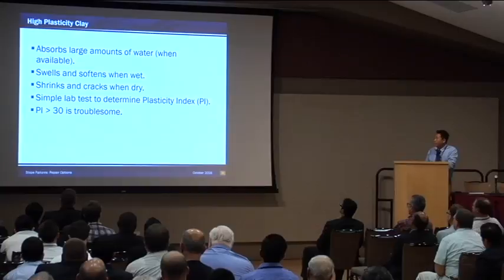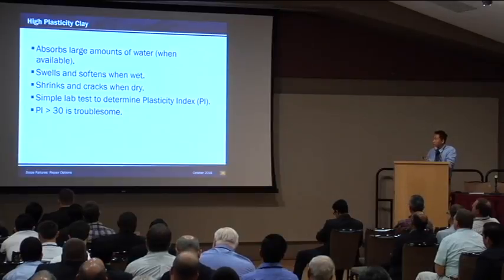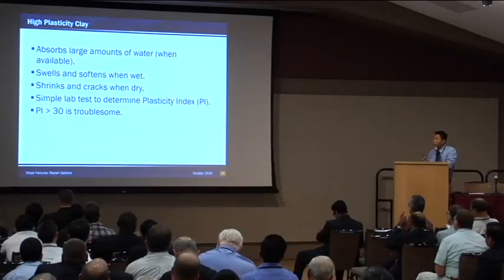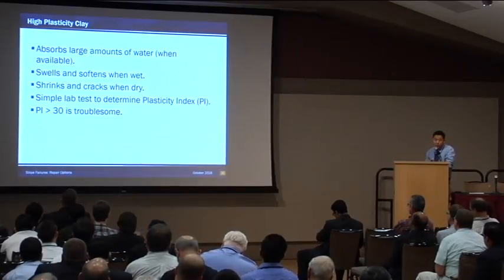Okay, the problem of high PI clay is that it absorbs a large amount of water, and it swells and softens when it is wet, then shrinks and cracks when it is dry.